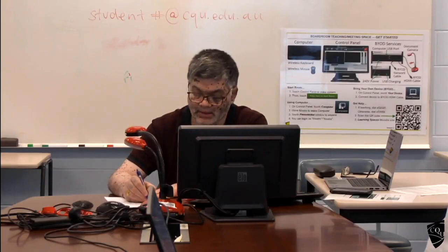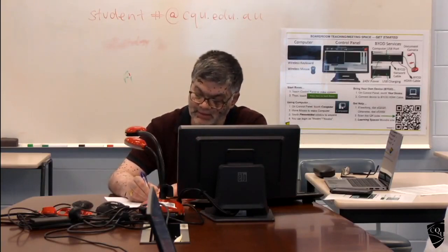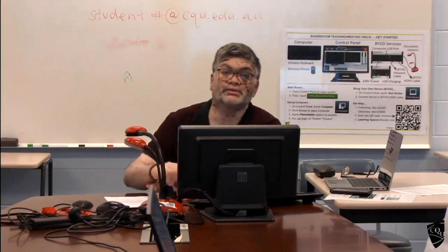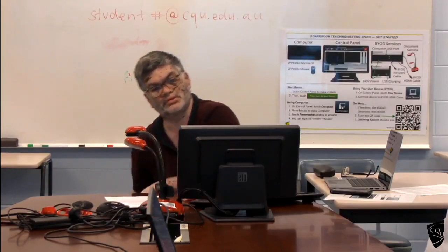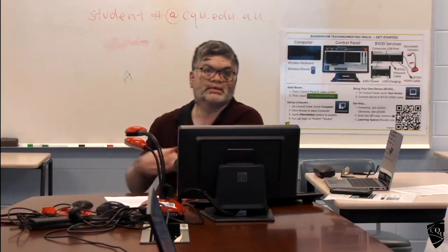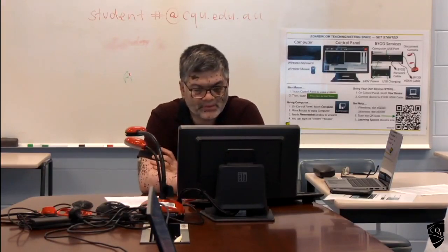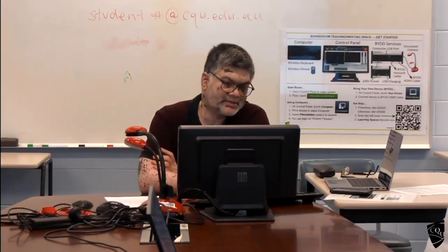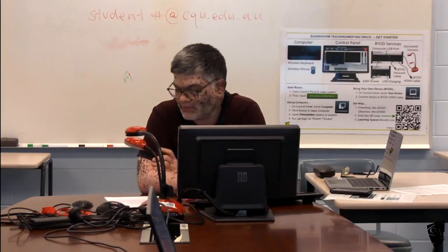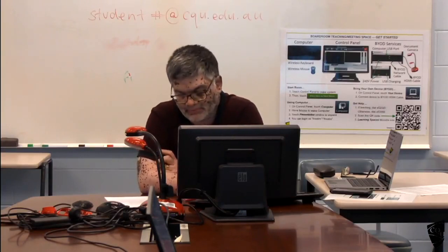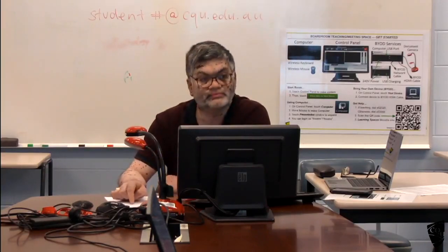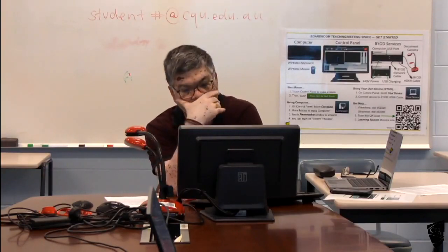Okay, and if you look at this one, this is a middle strip, so we may have three types of zones: CC, column to column strip intersection; column strip and middle strip intersection; and middle and middle. Okay, so if you look at these three intersections, the column to column, normally it will be around the column area. So that is the more critical one.